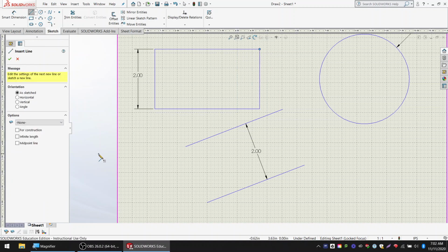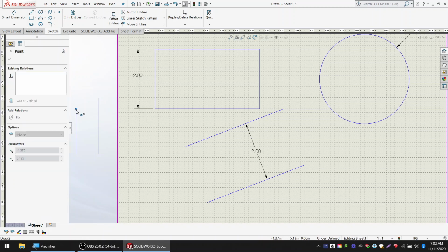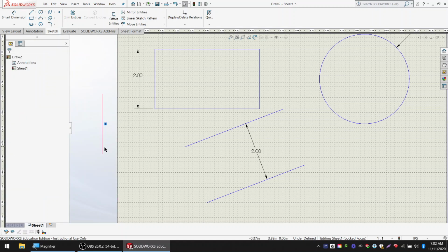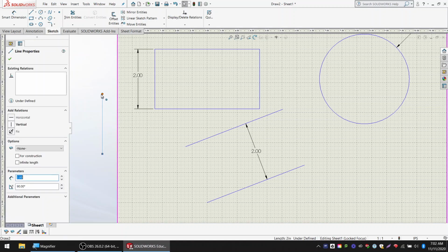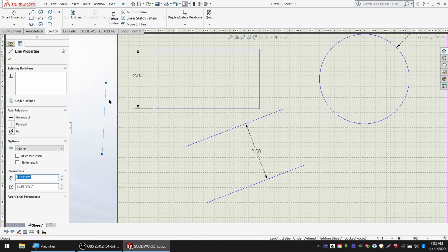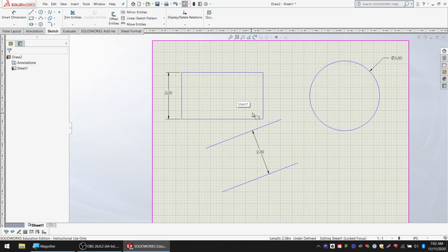I can show you this with the line too. Okay, so if I snap this to be vertical, then when I try to move it, it'll move around, but it won't change. Now if I delete this green square, same thing, it turns orange, click on it, turns light blue, and hit delete. Now I can move it to angles and I can move it around however I want. So if you're trying to move something and it's not working, it might be because one of those little green squares is on it that is constraining it and making it so that it cannot move.